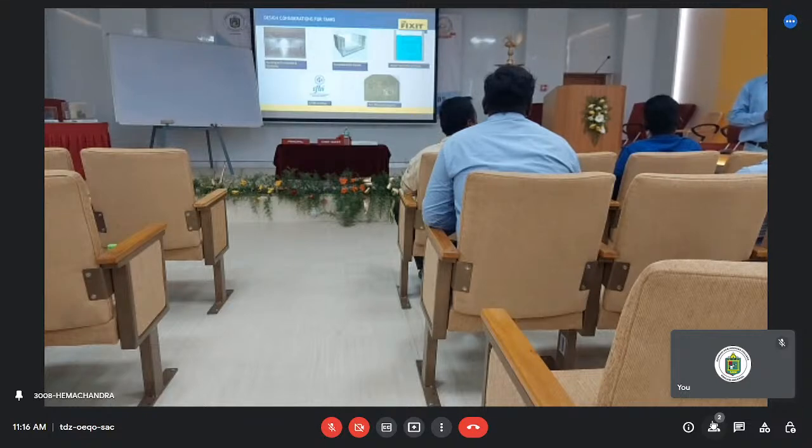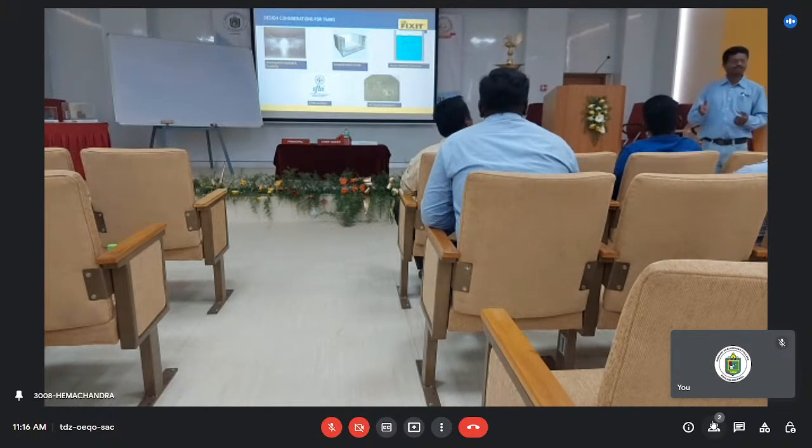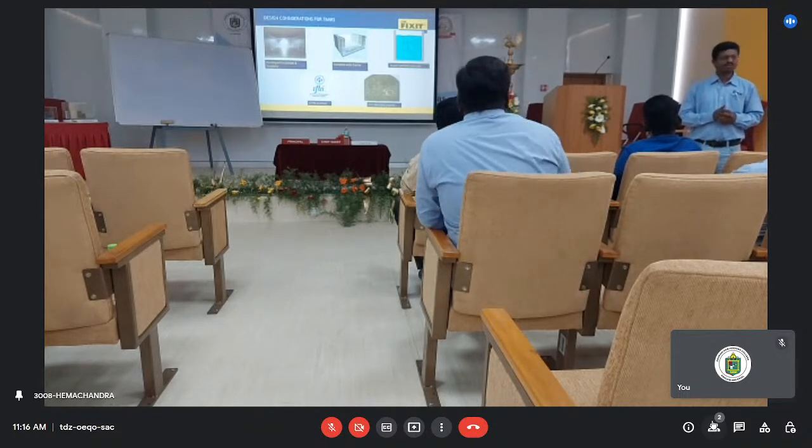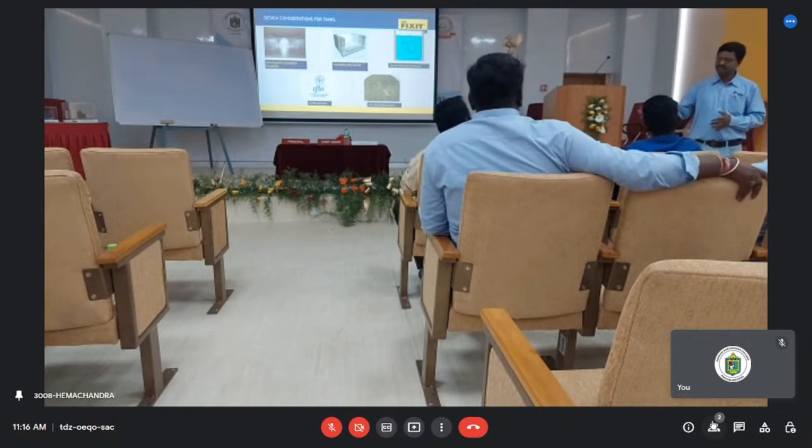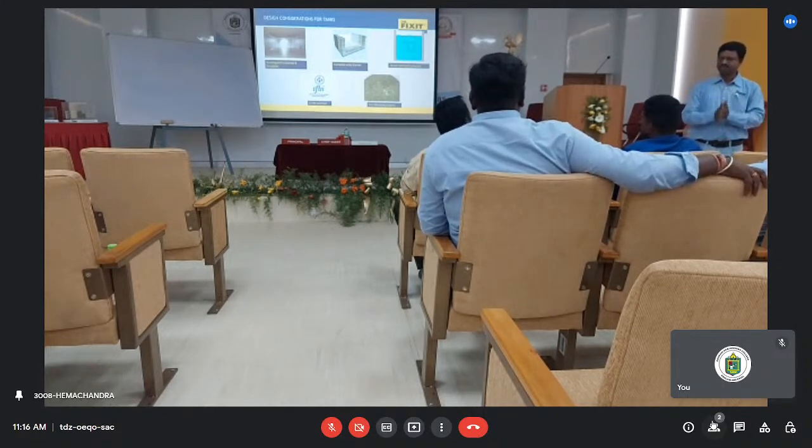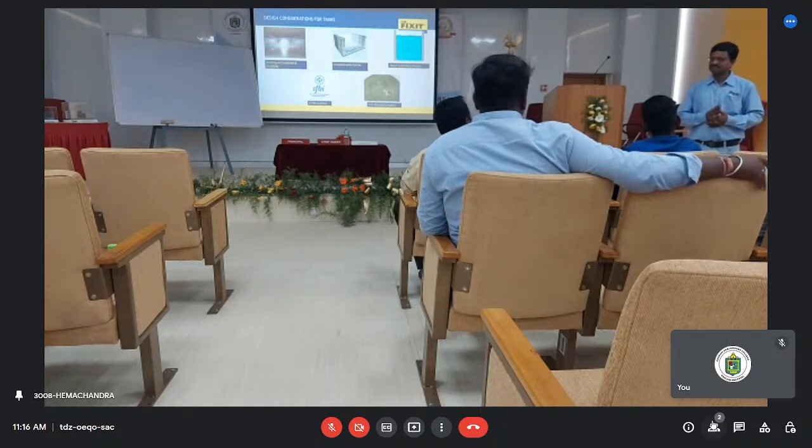What I meant is that we want to upgrade the system for engineering practice. A normal practice is brickwork only. People will say we constructed the sump in brickwork, now it is leaking, water is pouring out, and ask you to come and arrest it. It is very difficult to arrest. That's why we always want to construct an RCC sump. If it's an RCC sump, it is 150 mm or 100 mm thick.